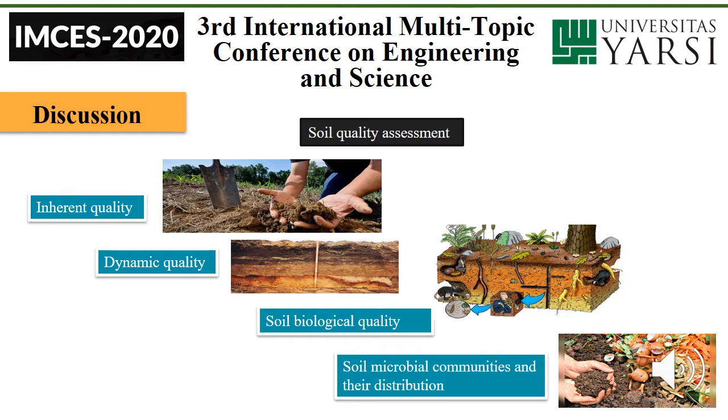Soil quality is an attribute that depends on the integration of different physico-chemical and biological properties, management effects, and cultivation system together with climatic conditions. The concept of soil quality comprises two components, inherent quality and dynamic quality. Inherent quality is that which results from the natural properties of the soil determined by factors such as climate, topography, biota, and parent materials. It is frequently used in the comparison of soils and to evaluate their suitability for different uses. Dynamic quality of land is that which results from changes in the health conditions of soil properties influenced by agricultural use and agricultural management policies.